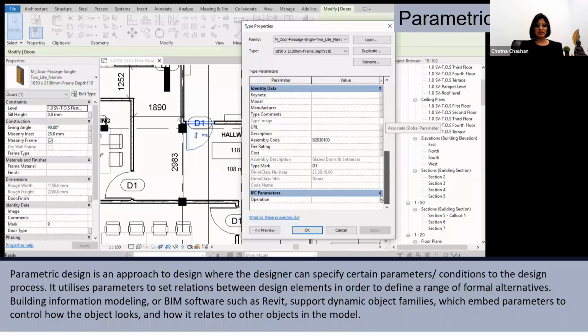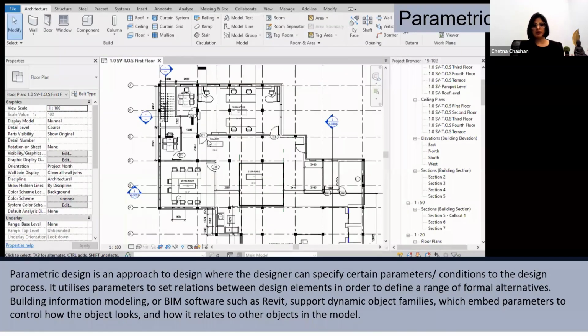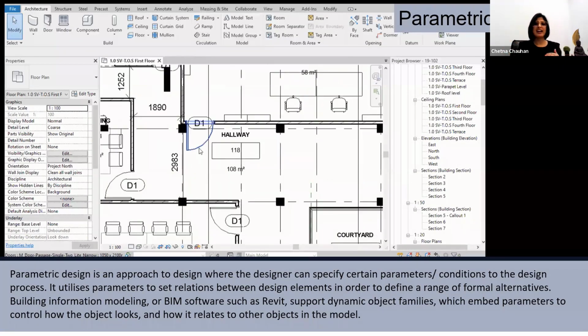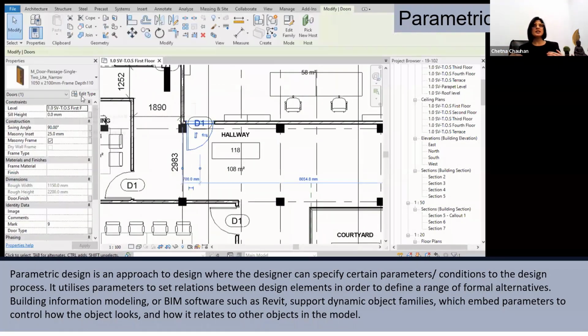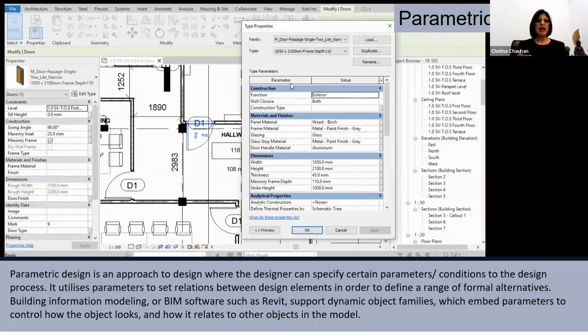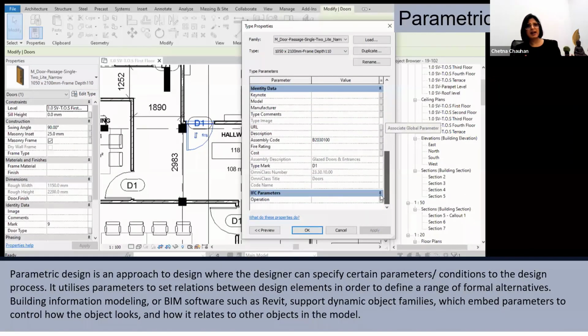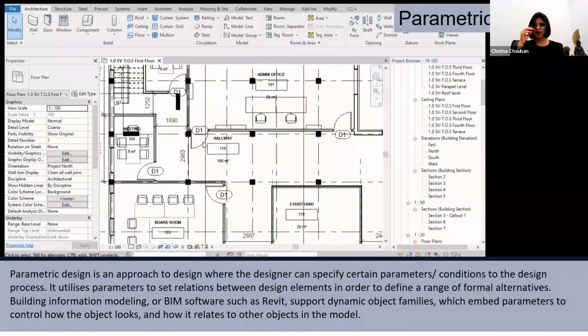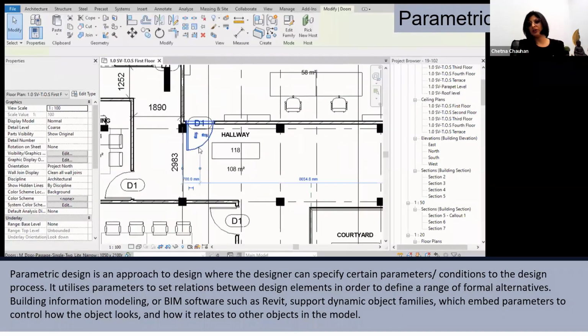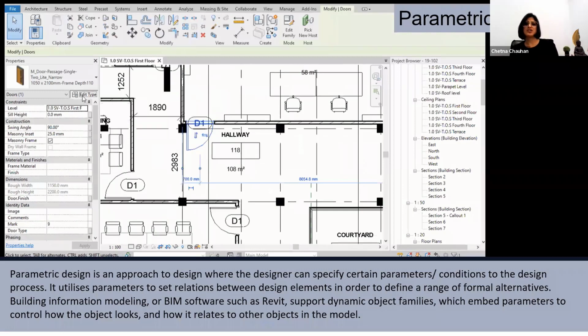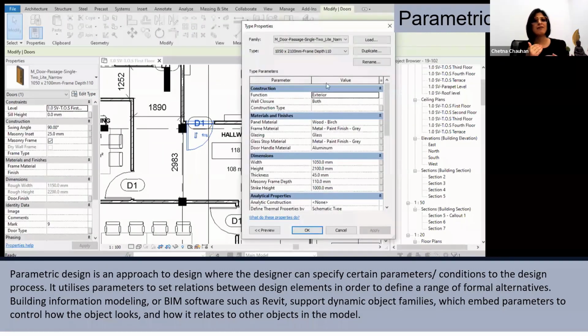So let's say in a small house, I say this is a 30 feet by 90 feet plot. I have to give a front setback of, let's say, 10 feet and a rear setback of 5 feet, and side setbacks of 5 feet each. So I have a square block. Now I want 3 bedrooms and 1 kitchen in it, and this has to be 3 floors.